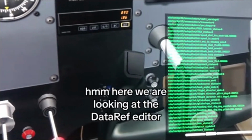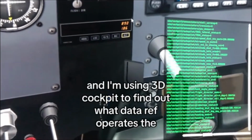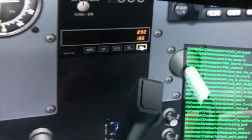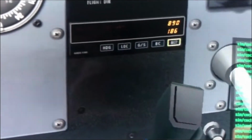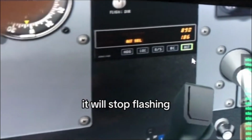Here we are looking at the data ref editor, and I'm using 3D Cockpit to find out what data ref operates the altitude control here. So when I click on this, I see altitude select. Click on it and it's not. So when I press the altitude select on mine down here, this will flash, and then when I press it again, it will stop flashing.